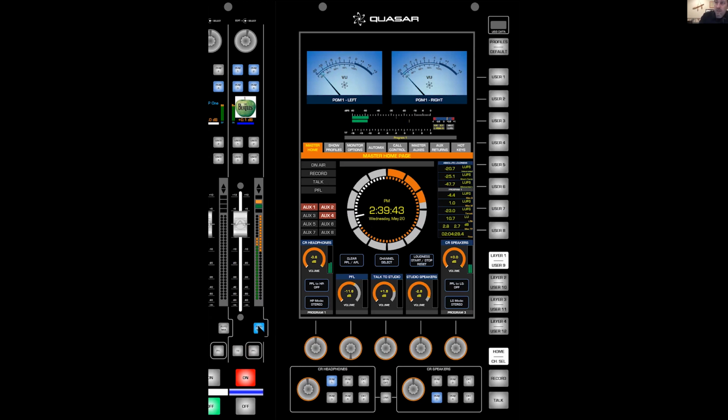It's great when I click this auto mix button and I start enabling the auto mix. You've seen my bar graph here has changed. What I have here on the left side of the bar graph is my pre-fader level. The right side of the bar graph has changed to a gain reduction meter, showing me what's happening on that particular fader's gain with respect to my auto mix being enabled.